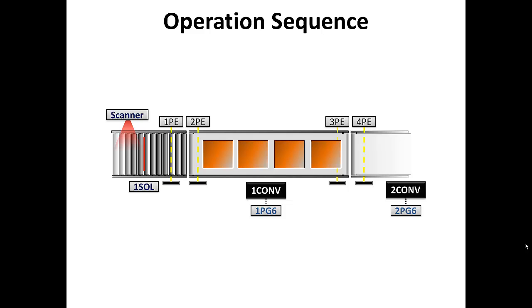So any carton that comes down the gravity conveyor hits the buffer conveyor and keeps right on going across to the takeaway, and away it goes, because downstream they're demanding cartons right now. But let's say downstream they have to stop part of the process to load up more labels for the box labeler, or some other part of the process downstream that needs some attention. You can stack as many as 4 cartons onto this conveyor, and then you can start pulling them off again.